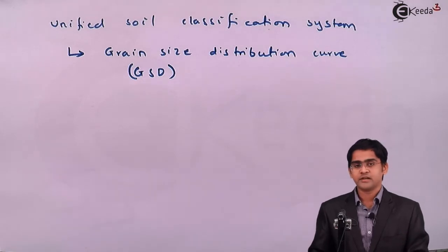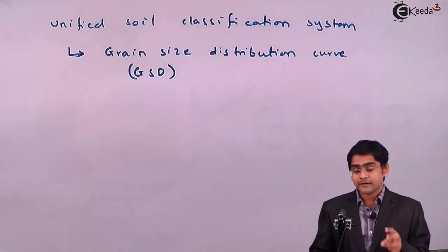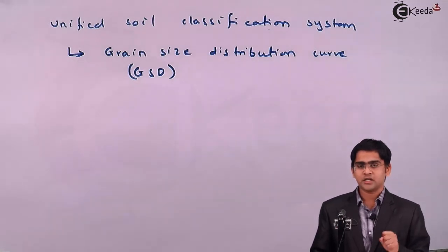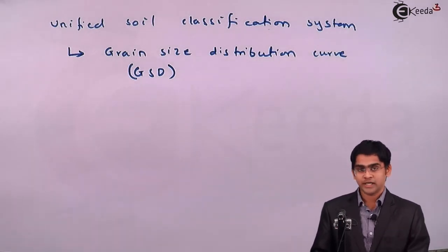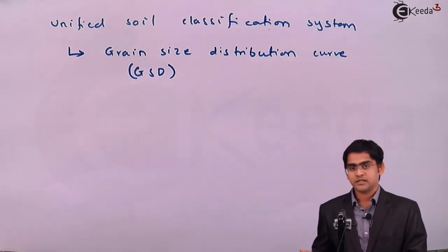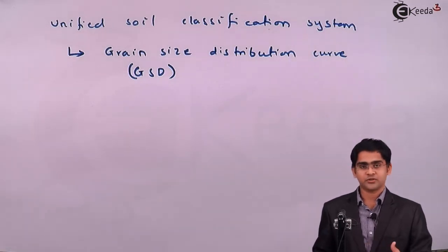In soil grain property, we have seen grain size, grain shape, grain specific gravity, and grain mineralogical composition. These soil grain properties are not dependent on the history of the soil. Vice versa, soil aggregate properties depend on the history or the formation of a soil.